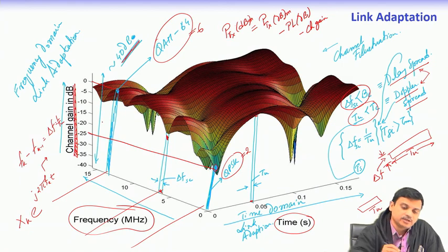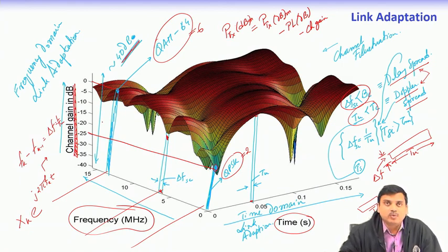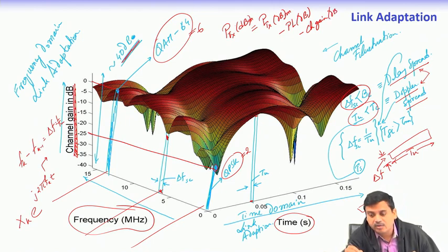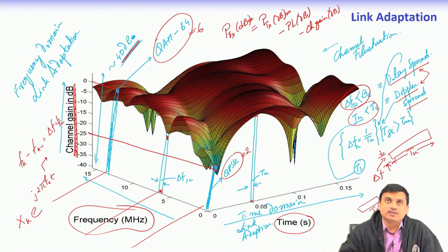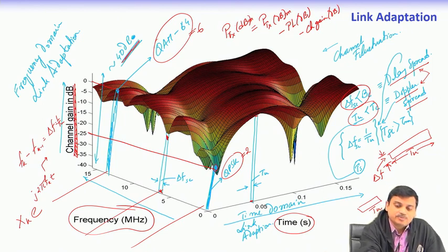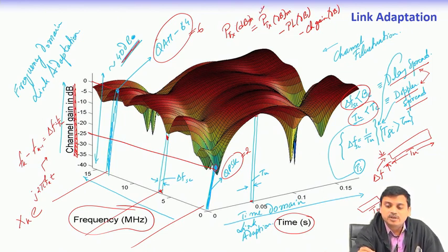What you see over here, the maximum channel gain is usually set to 1, that is normalized. Whereas what one has to do is that the average small scale channel gain is set to be equal to 1. So, instantaneous fluctuations will be there, in dB, and this is your received signal strength. So, to translate this picture to received signal strength, one must be given the transmit power, and one should also consider the path loss associated with it.